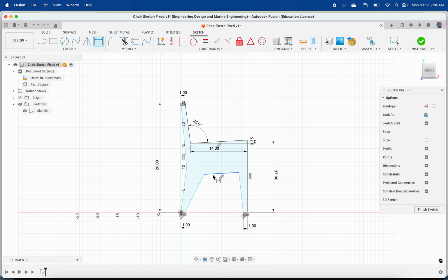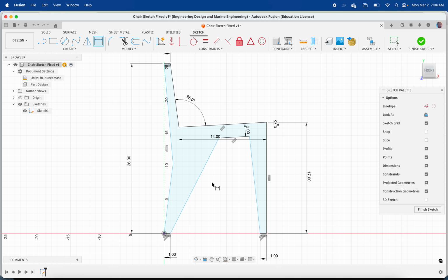This chair now has way too much structure underneath, so we're going to dimension that by controlling these surfaces to be 2 inches apart. And now the legs are a little crazy, so we're going to make this distance here 2 inches. This one's a little confusing because this point is very arbitrary; it can kind of go anywhere. So we're going to control it by giving it a flat line between the two. So we'll do a line between there and there.